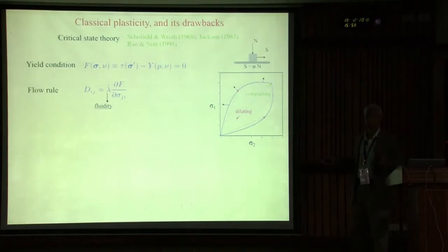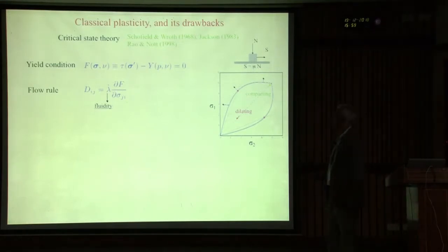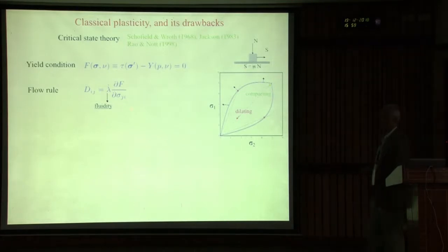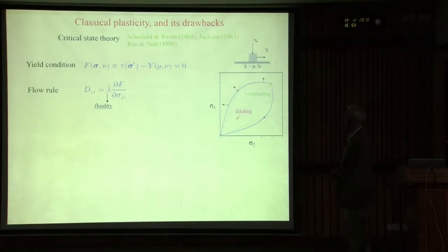This corresponds to the Stokes flow regime in suspensions or fluid flows. So the particle inertia is unimportant. You can take particle density and set it to zero, and that is an important regime because it occurs in many practically relevant flows, like flows through hoppers or bins, which are extremely important in handling of grains.